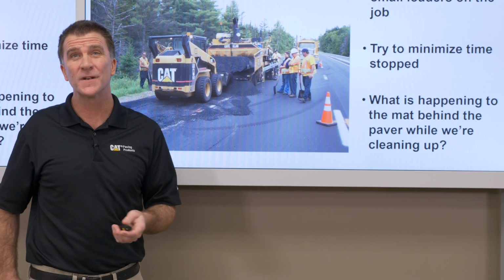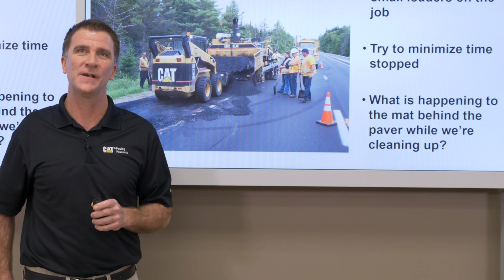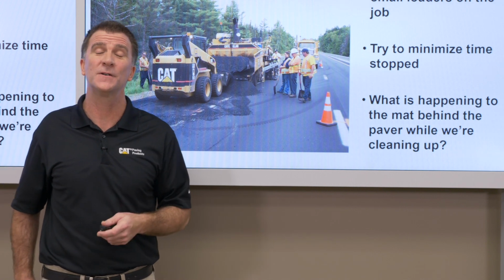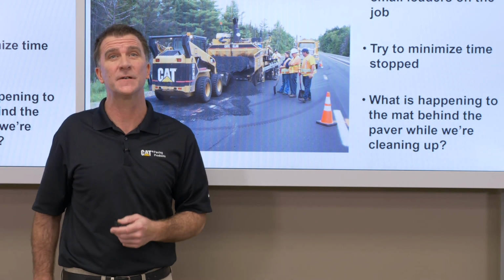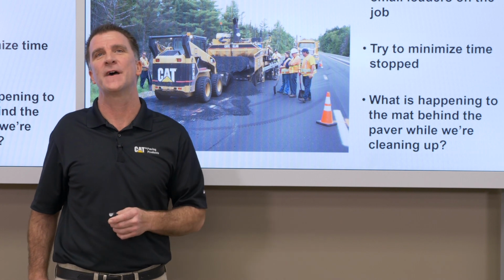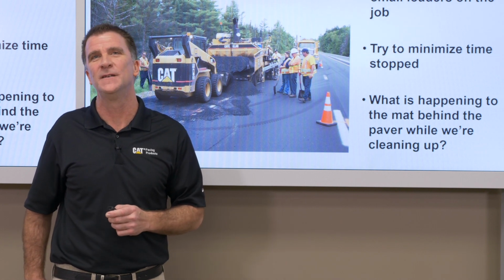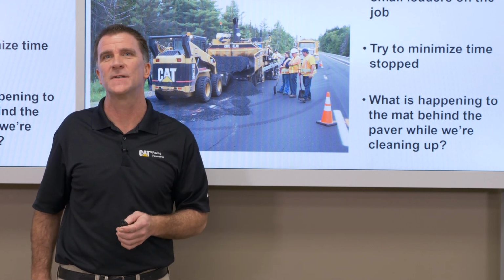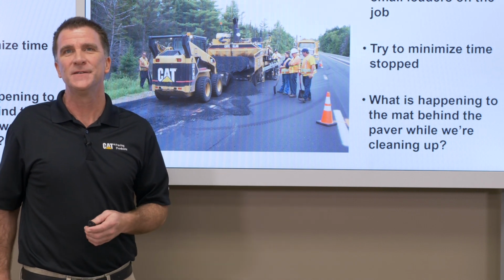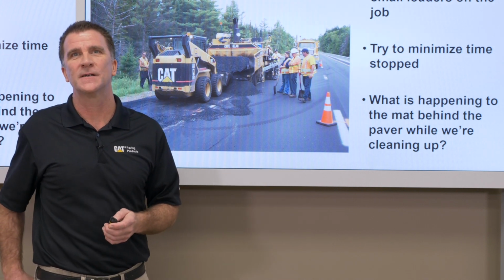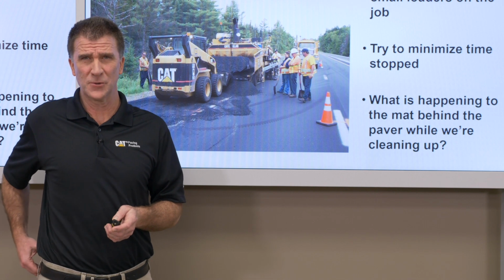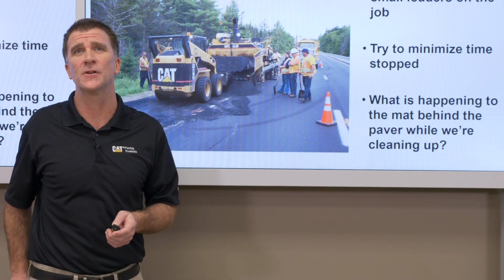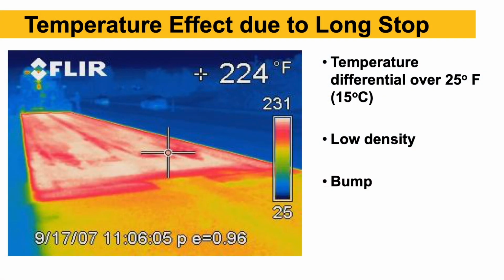We're going to have some lower density there where that mat got cold behind the screed. Probably not going to have a perfect cleanup here, so we'll pave over top of that and likely have some lower density areas as well. So just a lot of problems if we don't do the proper training and have good, clear communication with the truck driver. This slide just shows a temperature effect due to a long stop.